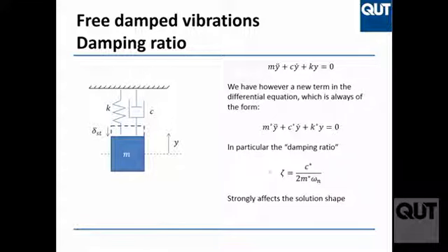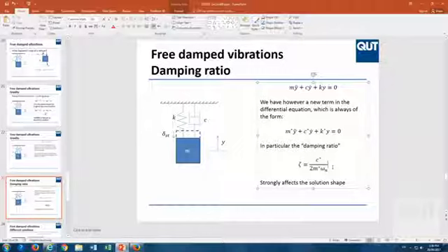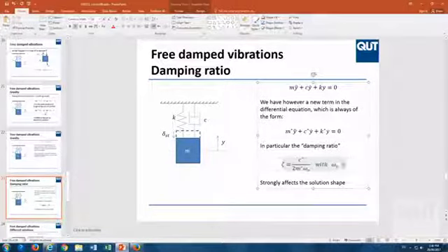Okay, that said, you have to calculate that damping ratio, which is this number, so the number in front of the y dot, divided by this number, omega n. How much is omega n? Same as before, with omega n equal square root of k star over m star.